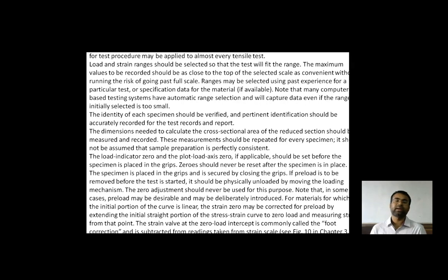So the load indicator zero and the plot load axis zero, if applicable, should be set before the specimen is placed in the grip. So zeros should never be reset after the specimen is in place. So the specimen is put in the grip and is secured by closing the grip.